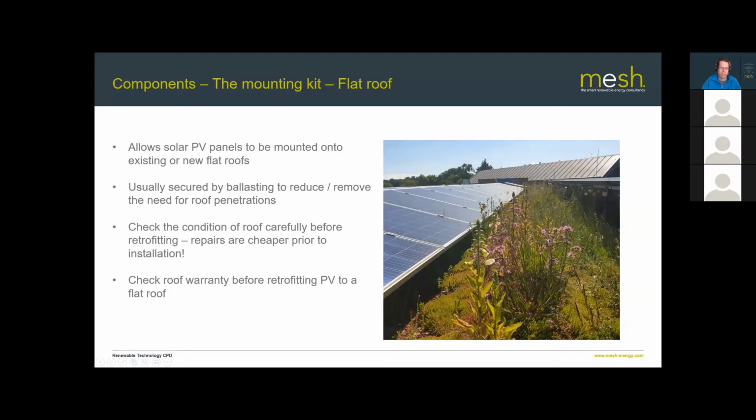So just check what the roofing details the roofing manufacturer needs, and quite often that will mean they'll ask you to put a sacrificial layer of membrane over the top of the actual weathering surface, so that if there are any little sharp edges, or if there is any movement of the PV against the roofing surface through thermal expansion, those kind of things, it's not going to wear through the membrane and cause a leak.